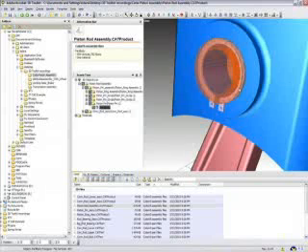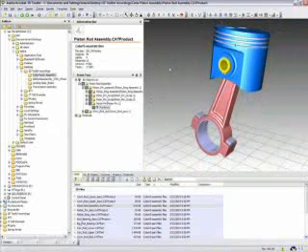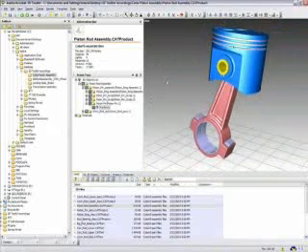As this example shows, the best practice is to import objects at a high resolution using the import options. Then, reduce the number of polygons using the Reduce Model tool. This procedure creates lightweight models that look smooth and are efficient inside the PDF.